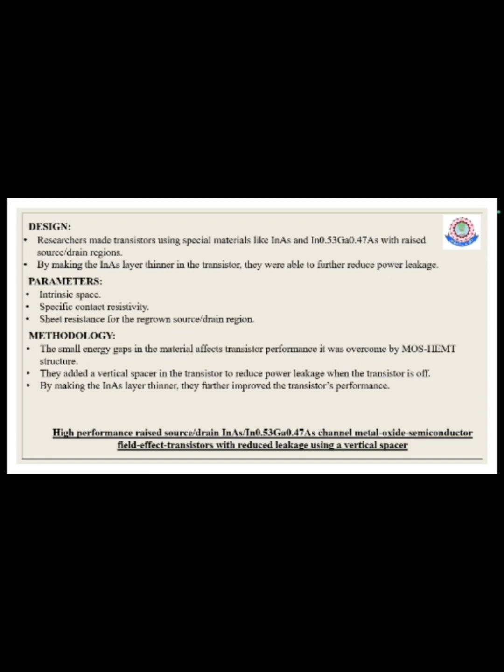They have successfully made the transistor using special materials like indium arsenide and indium gallium arsenide with raised source and drain regions. With that, they also inserted an intrinsic spacer made of indium 0.53 gallium 0.47 arsenide between the indium arsenide channel and the source drain region. This spacer helps to reduce the power leakage when the transistor is not in use. By this, the performance of the transistor is improved.